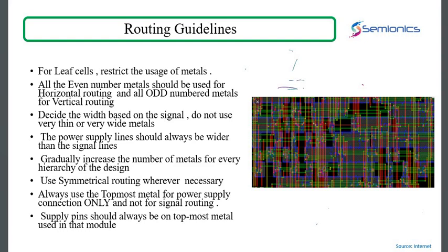And one thing to keep in mind is the power lines. Now the other concept here is the power lines. Always power lines should be slightly wider than the signal lines. That's another important thing to keep in mind. Now gradually increase the number of metals every hierarchy.